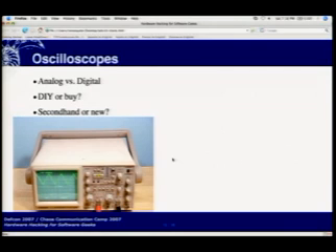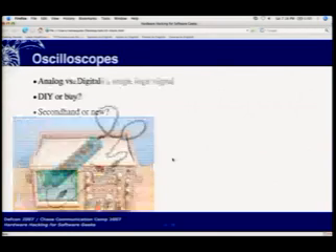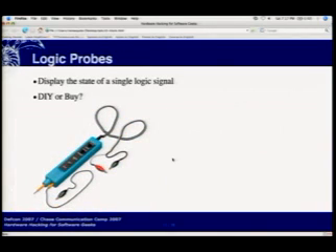Well, another alternative is to use USB-based oscilloscopes, but the display is not going to be anywhere near real time, and there's usually going to be a noticeable 3-4 second delay. Like if you're monitoring a serial port with it and you're trying to look at your frame size, and you hit a button on your console and watch it go on the oscilloscope, it might be 3 seconds before you actually see it. But those USB instruments can be very useful because it'll only be a couple $100 rather than tens of thousands of dollars for the equivalent full instrument that you'd see in a lab.